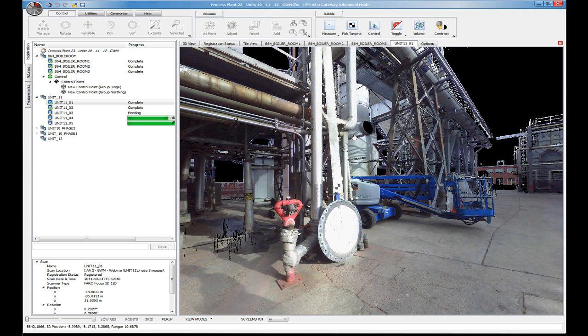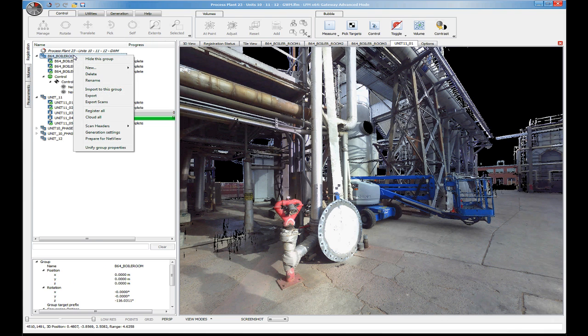These consist of individual scan export to PTX and E57, LFM server dataset generation, and LFM NetView project creation. In the interest of time, we will not show you the actual execution of these options live, but will show you the way to access these options via the LFM server interface. For this example, I will use the boiler room scans.